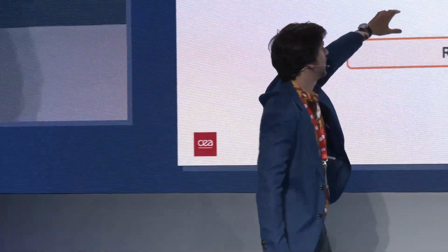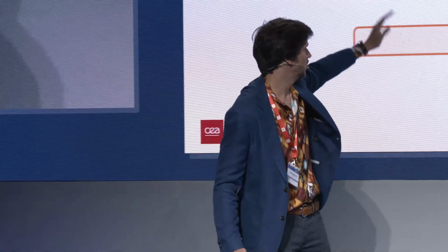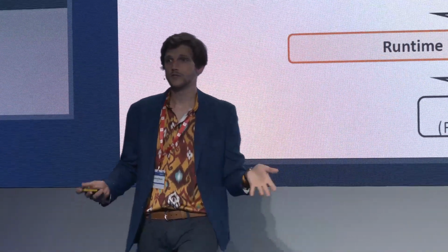Now we offload this job to our architecture, where there is standard C code, up to the point that we want to call the kernel, the BLAS library, to solve the linear system with a large matrix. And here we provide a BLAS routine, where basically we have written in assembly all the instructions, scheduled in such a way as to minimize the latency as much as possible, and then we run on the hardware. But we didn't stop at the hardware.